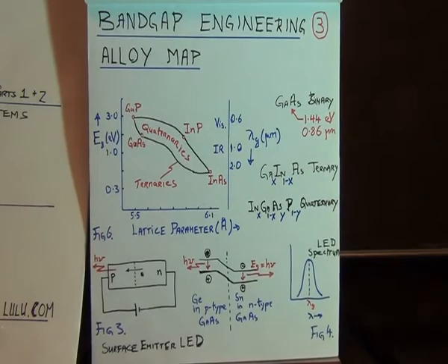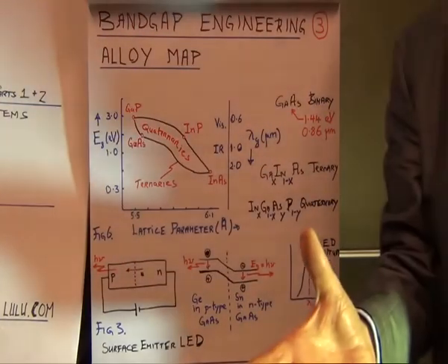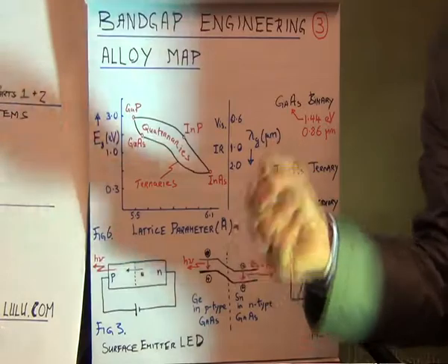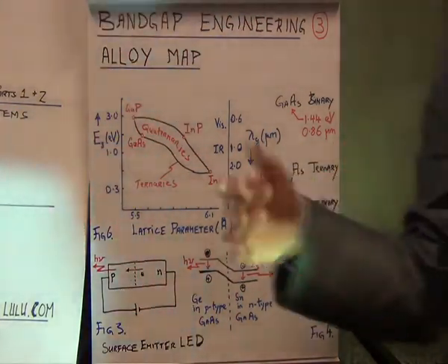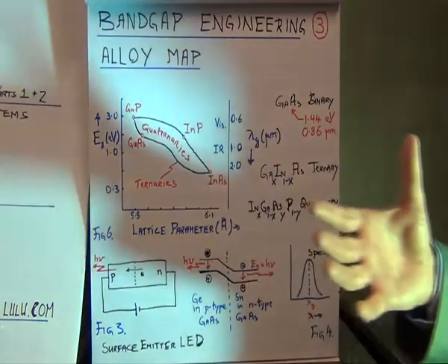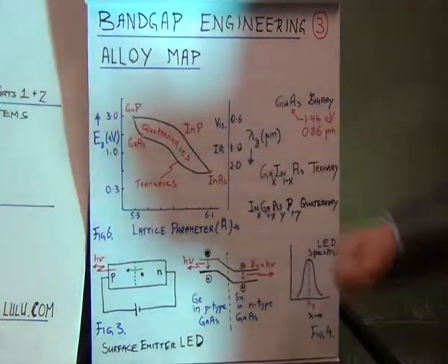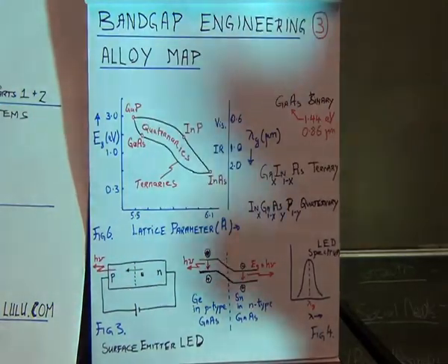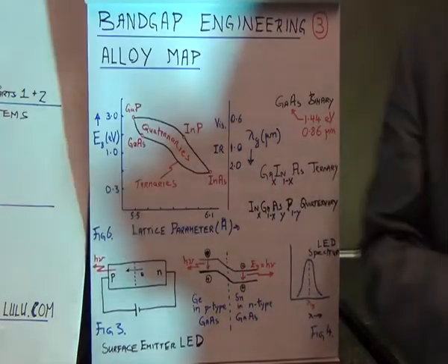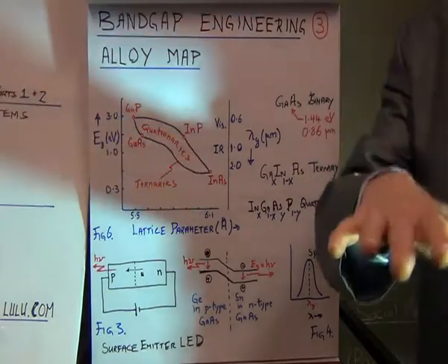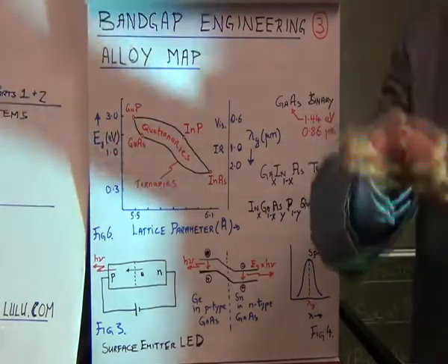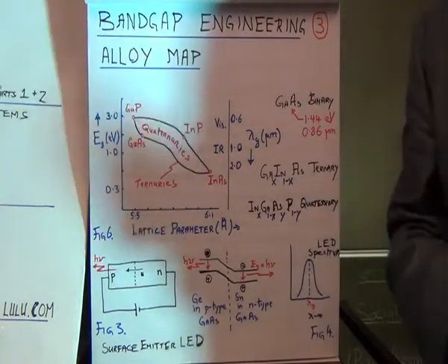The way you would do it is you take a vacuum chamber. It's a bit like how we grew our optical fiber. In fact, optical fiber technology derived from the semiconductor technology. You would inject gases, carrier gases for gallium and for arsenic, into the vacuum chamber, allow them to react, and deposit a layer of gallium arsenide, and another one, and another one, and another one.